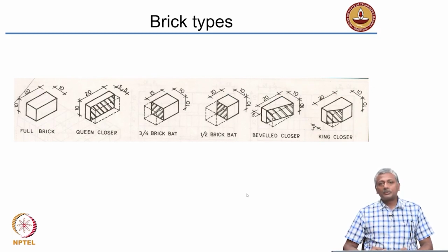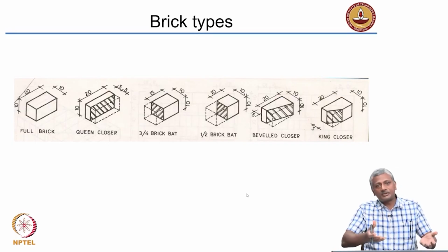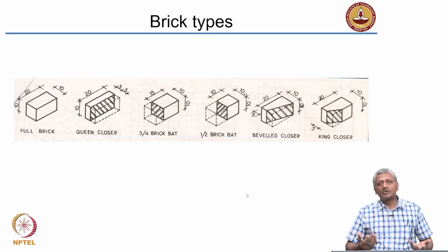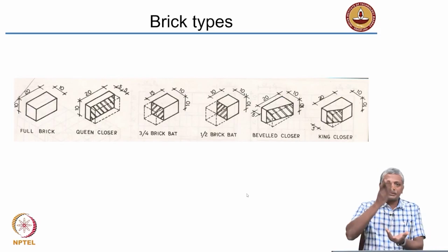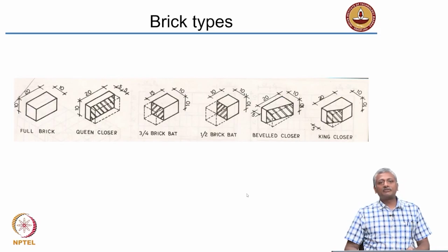There you will see that there are needs for special type of bricks to be used to get the kind of shapes that we actually want. Okay. Now in many cases you can mold these bricks into these shapes also, but then how many of these molds can you actually have on site, right. So oftentimes you need to have expert masons who have the capability of actually using their trowel to simply slice these bricks into different sizes.